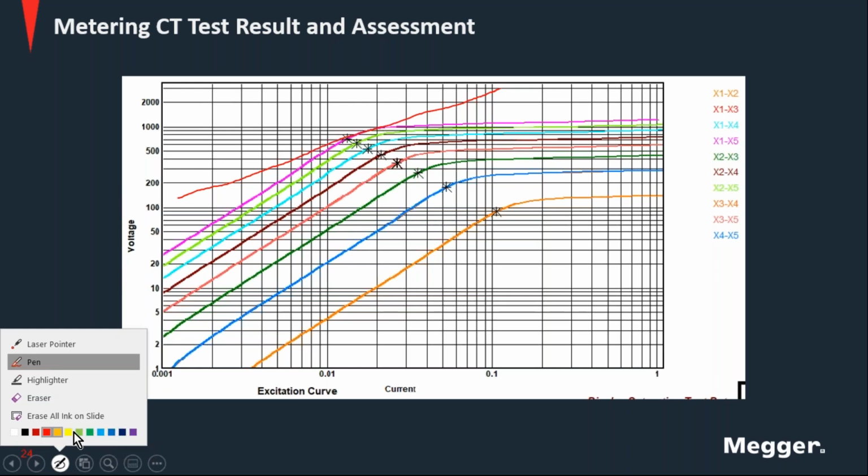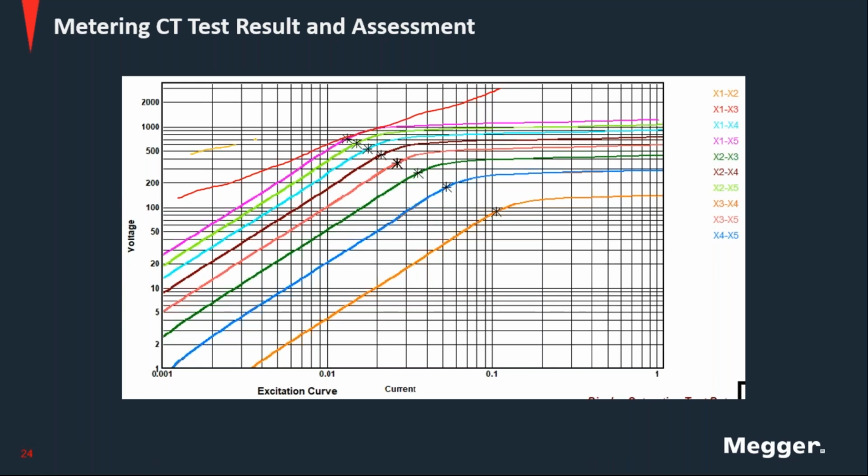The knee point of current transformers. The number indicates the angle or slope of the straight line from the coordinate origin at which a tangent line can be drawn to the excitation characteristic. So for ANSI 45, you would take a line that has a 45-degree angle, and you would have it touch the excitation curve in just one point. That's the definition of tangent, and that would be your knee point.